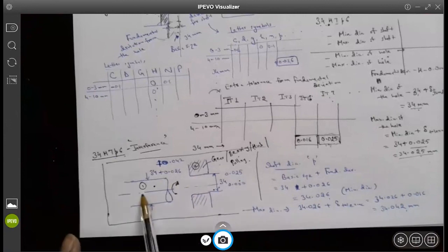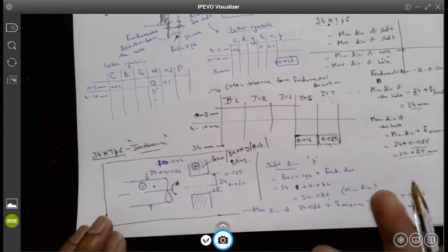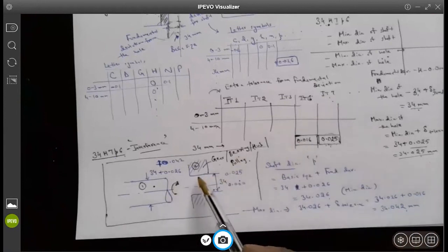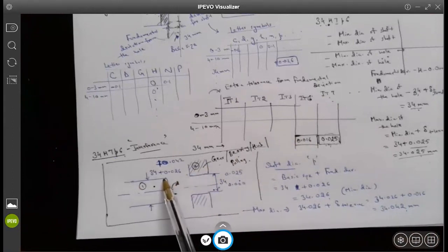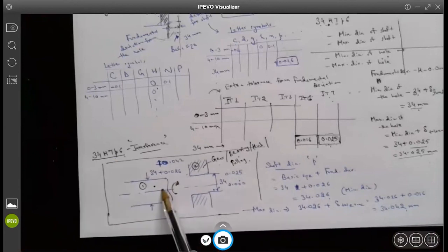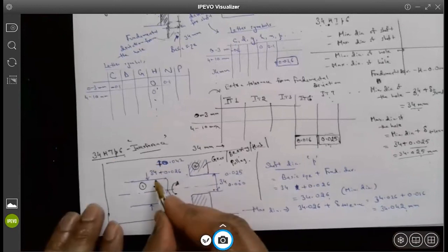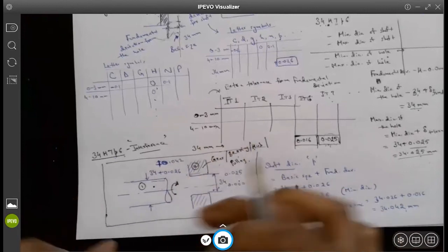Obviously, if you want to slide this component together, you will not be able to do that. So there are different ways of assembling these two parts together. You basically use a press fit, or basically press the two parts. You hold one part stationary and you press it. Because the materials are elastic, there will be some deformation in the materials, and eventually they will get assembled together. This part will slightly deform, and this will also slightly deform, and then they will stick together.